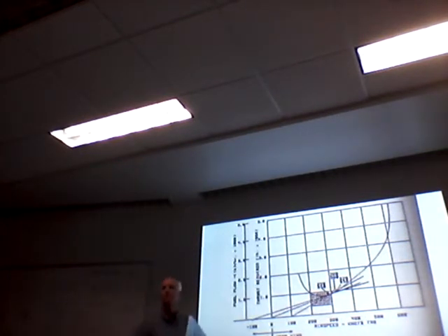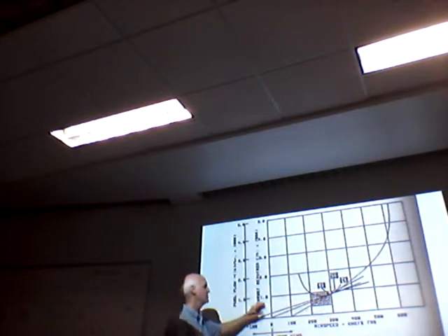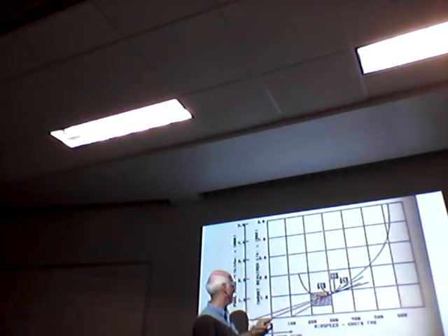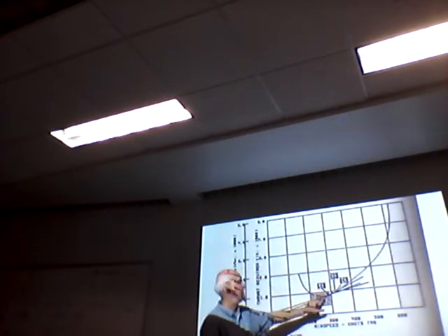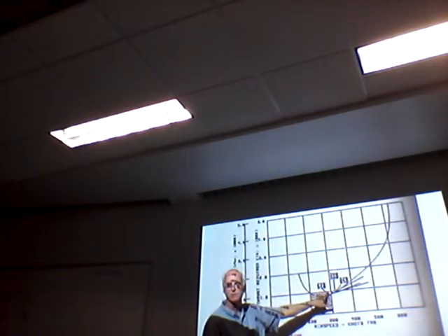What is 100 knots by 300 over 900? Those are fuel flows. Don't worry about it. Wherever that tangent is, the speed, that's what you read down here. That's all you care about. When I say tangent, I mean where it's touching. If I draw a line straight from the origin and wherever it touches the bottom, notice it can sometimes be kind of hard to read. There's kind of a range, but wherever that touches first, that's tangent, right?